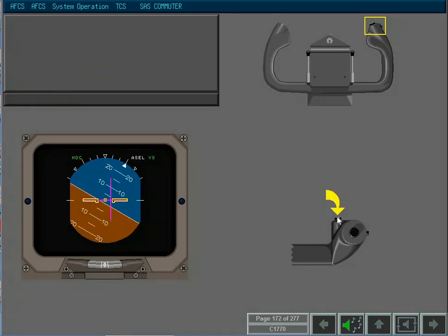During TCS operation, the flight director pitch command bars are zeroed to the aircraft symbol. Movement of the control wheel maneuvers the aircraft. Note that in vertical speed and IAS hold modes, the air data command display is removed until TCS is released. When the TCS button is released, the flight director pitch command bar indicates the pitch attitude required to maintain the new vertical speed, IAS or altitude.